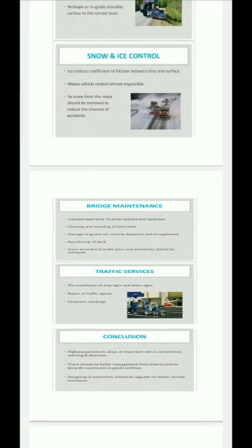Next is bridge maintenance. Exposed steelwork must be cleaned and repainted. Cleaning and resealing of deck joints, damage to guardrails must be repaired and strengthened. Resurfacing of deck, scour around and under piers and abutments should be removed. Traffic services: the installation of stop signs and other signs, repair of traffic signals, and pavement markings.